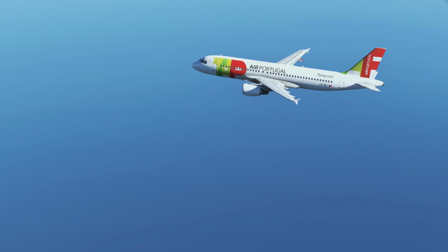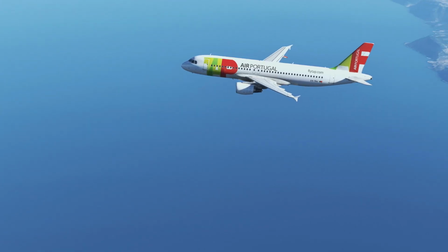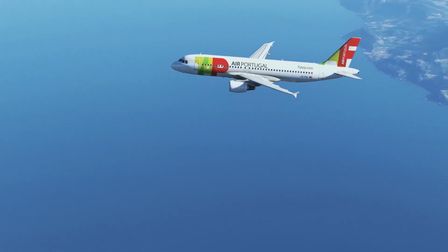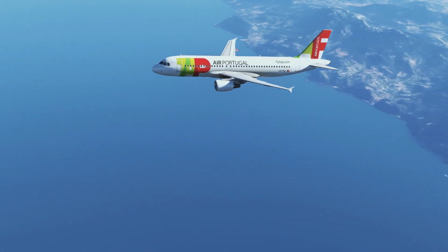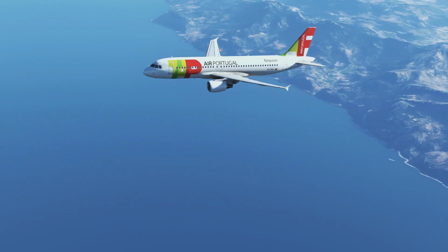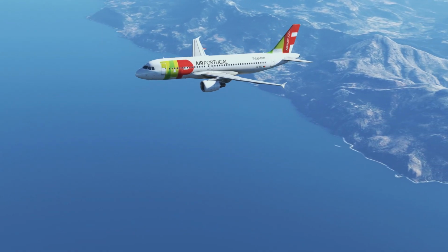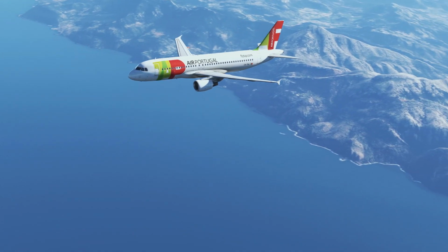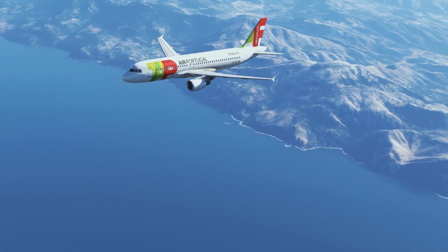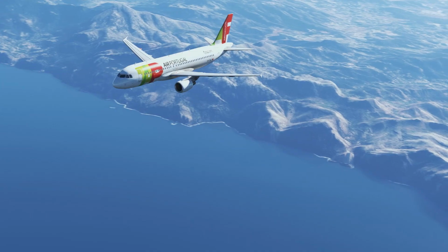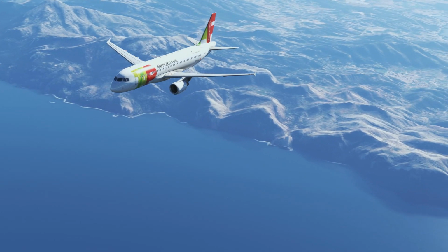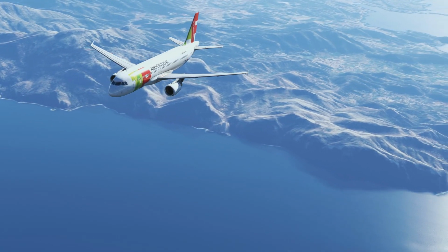Very often there's a lot of traffic, so ATC will take us off the STAR and give us some radar vectors. Sometimes there's not so much traffic and we get huge shortcuts that cut the entire arrival route down from, let's say, 80 nautical miles to 40 nautical miles, and all of a sudden you are several thousand feet too high. So all these things play out in the real world.